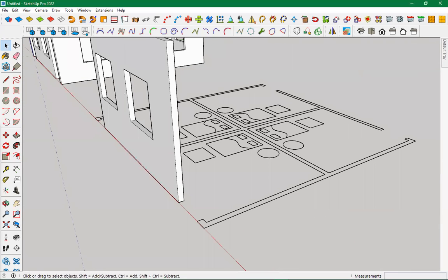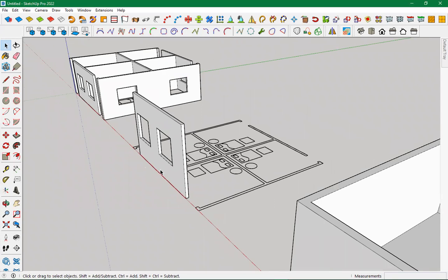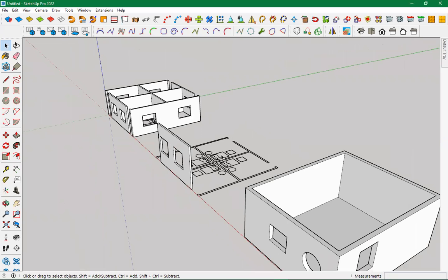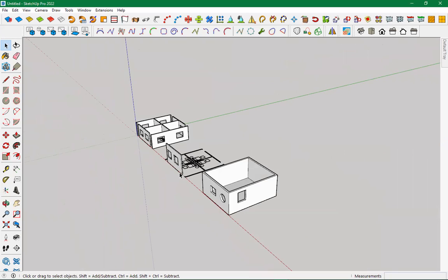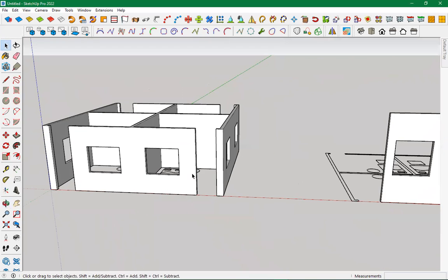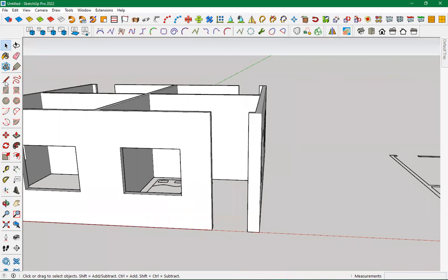What's the time? We have 4 minutes to go. Okay, so we've gone so far with this. So we've understood to this stage. And with this, you can actually create your doors. Let me do that quickly. Let me just create a door here. You know, the door should be 2,100 up to this point. So I pick my tool, I do this and make 2,100 for the lintel level. And from there, I can create a rectangle like so, down to this point.